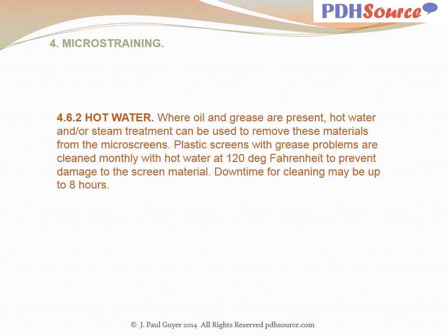Where oil and grease are present, hot water and/or steam treatment can be used to remove these materials from the microscreens. Plastic screens with grease problems are cleaned monthly with hot water at 120 degrees Fahrenheit to prevent damage to the screen material. Downtime for cleaning may be up to 8 hours.